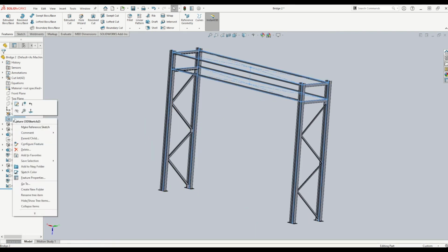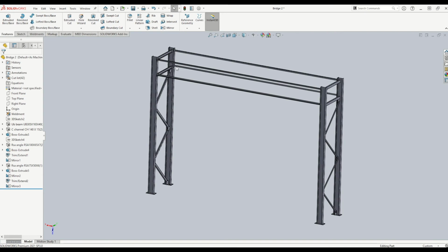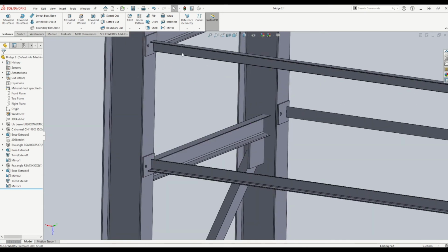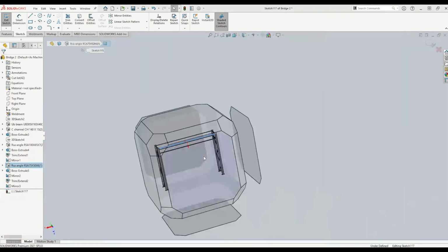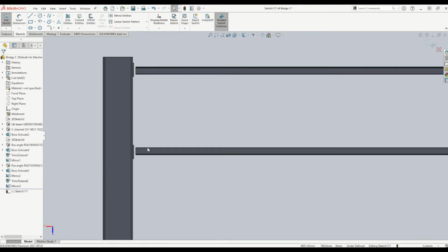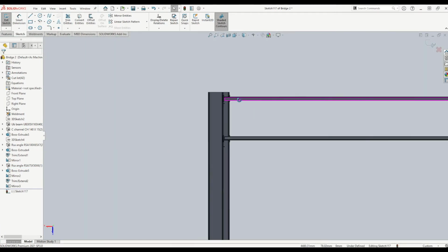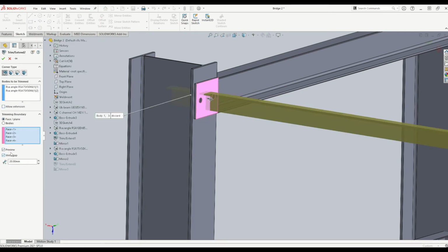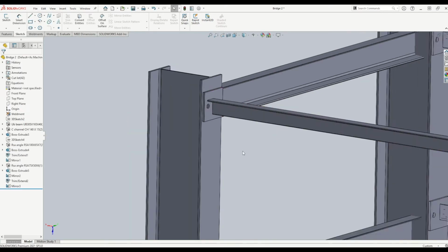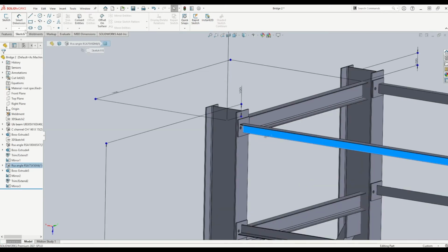So now I'm going to do some reinforcement struts. To do that, I'm going to draw a sketch on this. So this is a 2D sketch, not a 3D sketch, on this face. I don't know why it does that and spins it around. As you can see, I've just realised I've made a mistake. I've put a weld gap of 20mm in on my trim. So I'll just quickly exit that and get rid of the weld gap so it's flush.